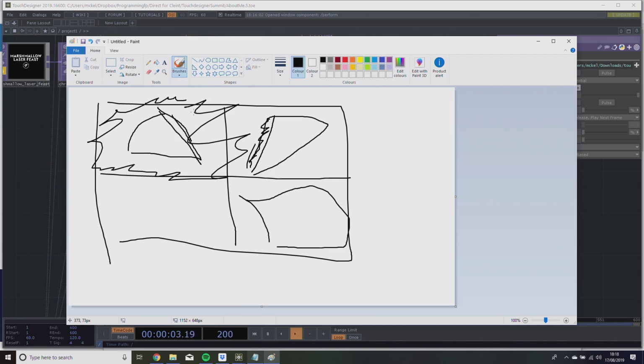but you can then just keep increasing the blur width until you get to a position where you're comfortable with it. Content plays a big part in what you're showing as well. A typical planetarium has a lot of dark imagery, so normally you'd never even see it. But if you're displaying pure white content, you're going to notice those hot and dark spots really badly.